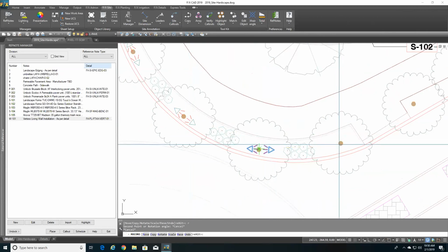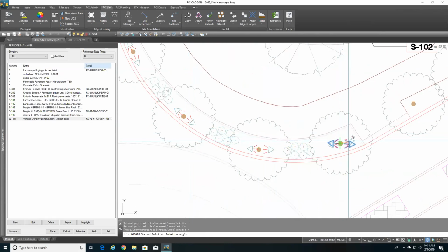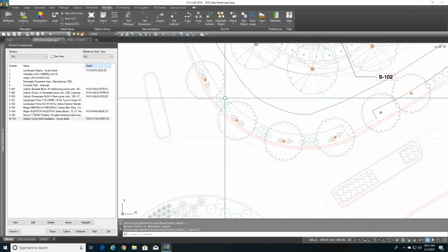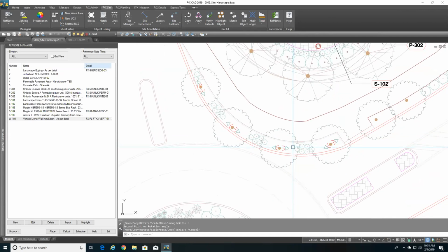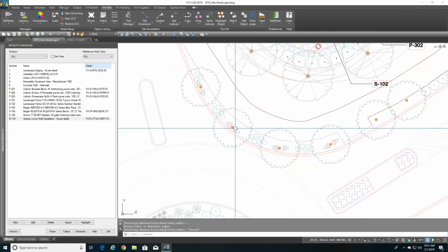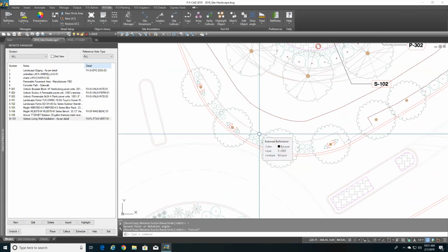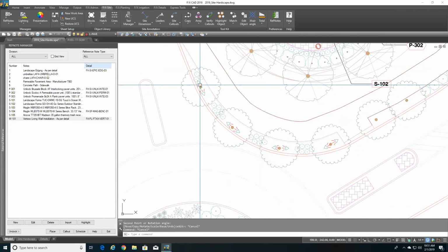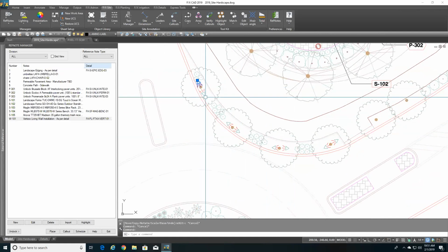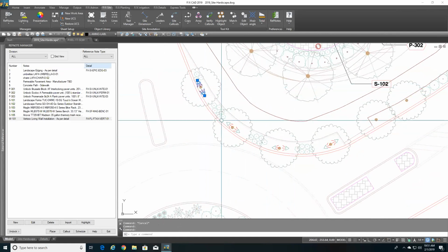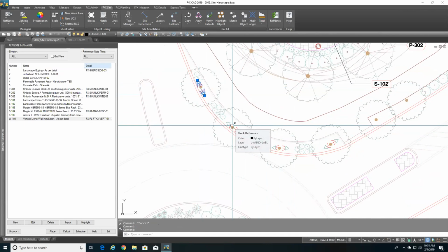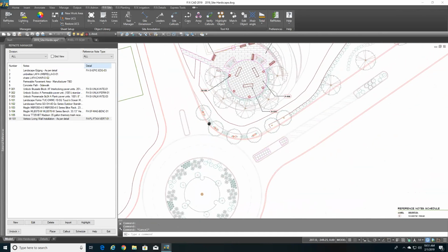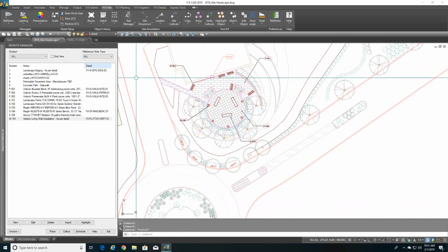Oh, I selected the wrong option there, but I'm going to hit C and hit that last trunk, maybe get a little better rotation on it, and instantly placed 8 fixtures, all spaced the same distance apart and rotated by group, which just speeds things up. I mean, just having to do that manually, clicking the individual one and then typing rotate, or grouping the two and then going copy across to this one, just cuts down the time so much and really makes things way, way easier.